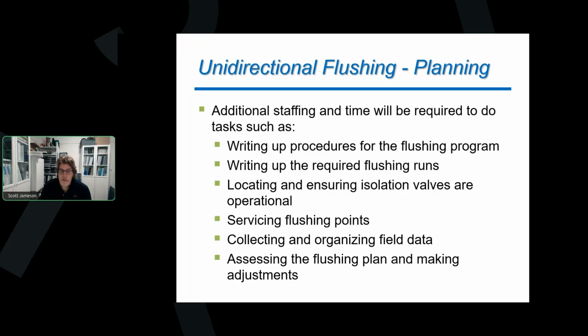Someone is going to have to go out and locate and ensure that the valves that we are marking out on the map that we need to close, that we know where those are and that those valves actually operate. We're also going to have to go out and service those flushing points, right? We're going to have to make sure all those points that we're going to flush from are going to work for us.